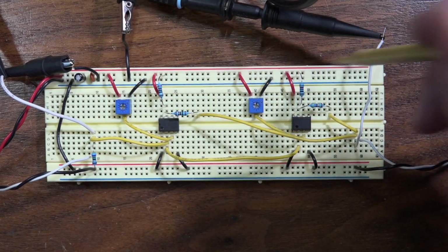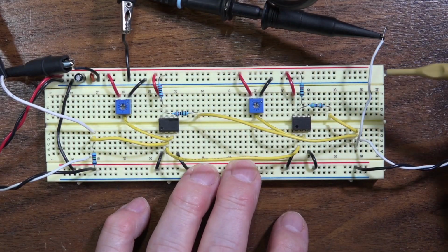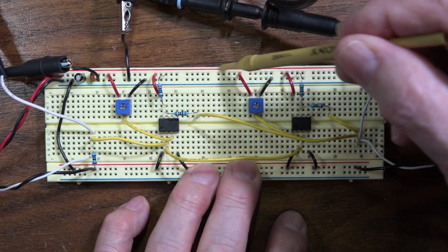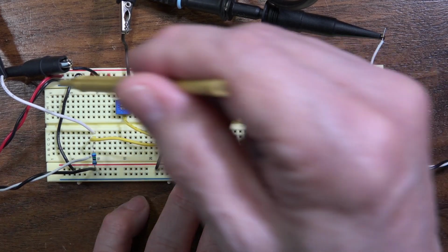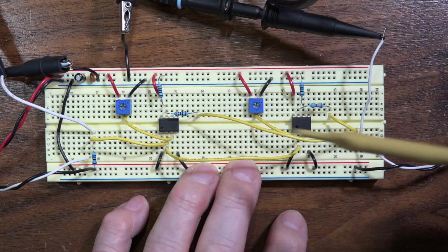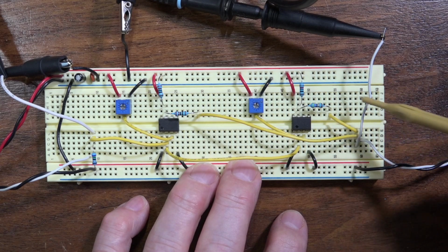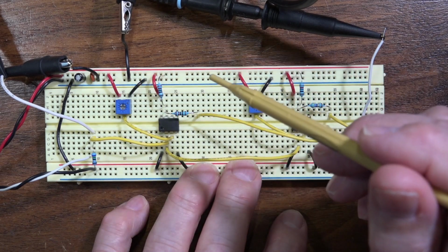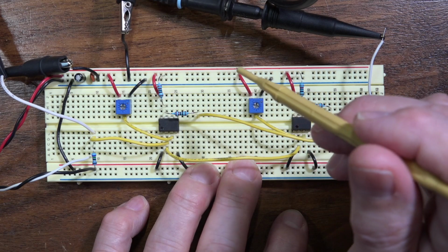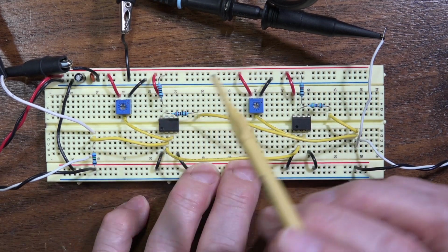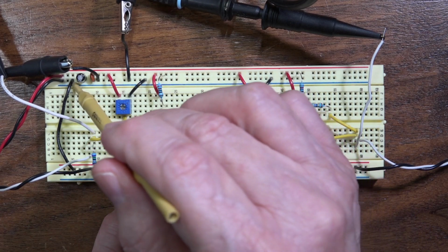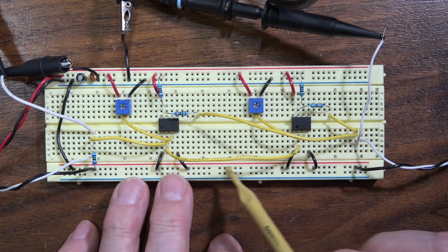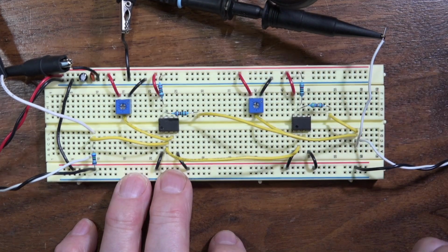So one rail across the top here, this is a breadboard. And these guys that go across the top, we call them rails. Big important word, rails, we're going to get to in a minute. That's a rail, and everything across the top is going to be red. That's going to be 5 volts. The next guy down, I make it black, and black is the ground. Black is 0 volts. Ground is so important, I'm going to bring ground down here, so we've got it on the bottom as well as the top.